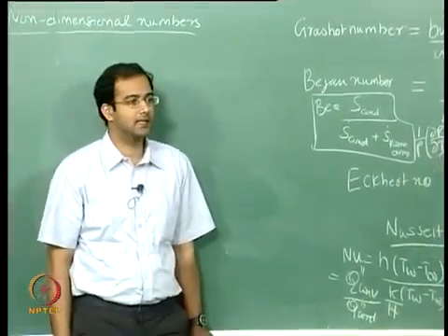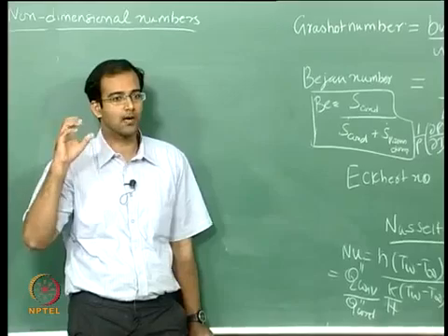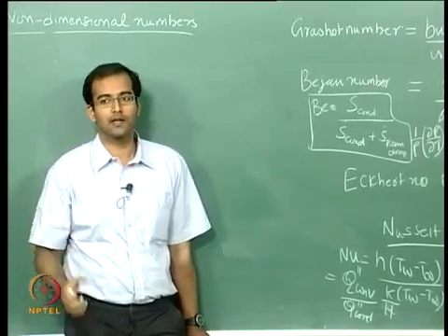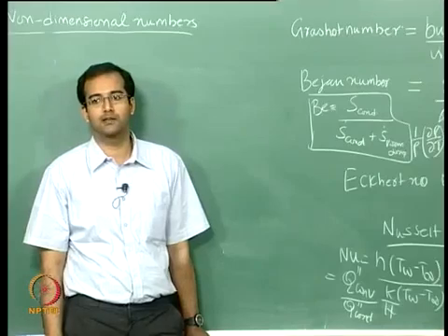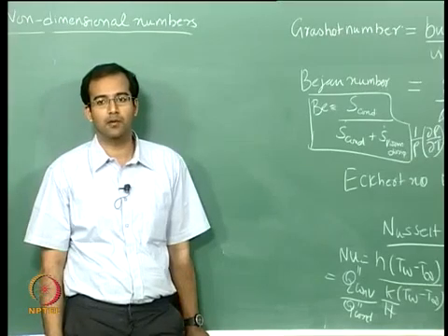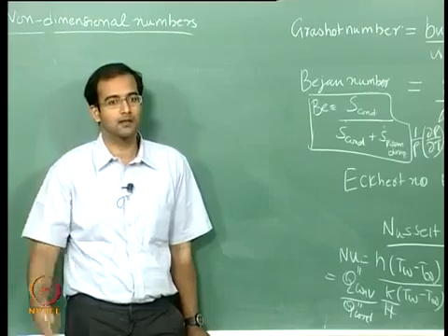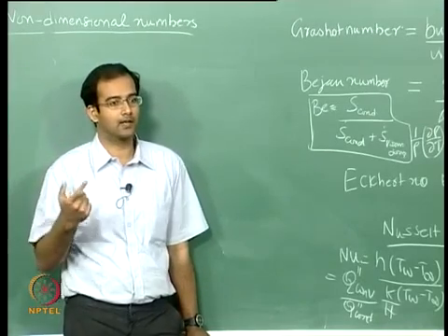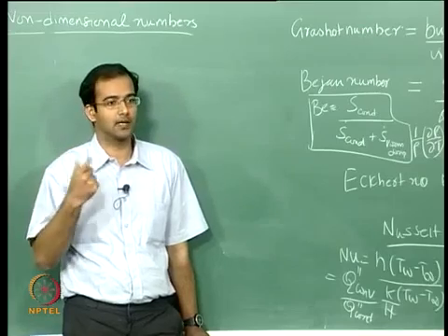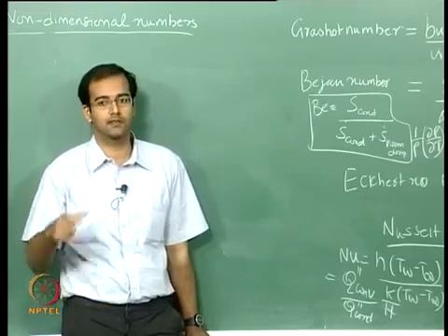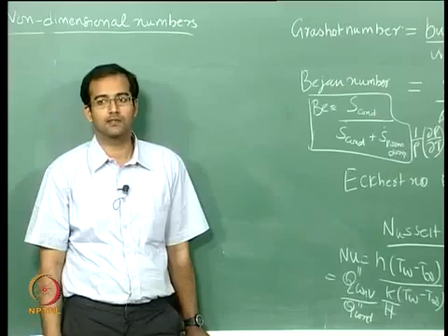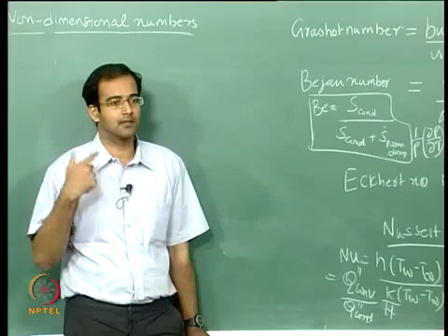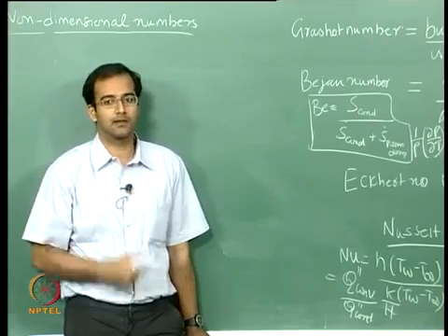So essentially it characterizes and quantifies the entropy generation contributed by conduction over the total entropy generated. So this is a very useful number. So far, people have been talking about entropy generation qualitatively, but now you can calculate the actual values from conduction and from viscous dissipation, that is the friction of the fluid which is generating entropy. You can calculate the contribution of each, and then you can take the ratio and that gives you the Bejan number.